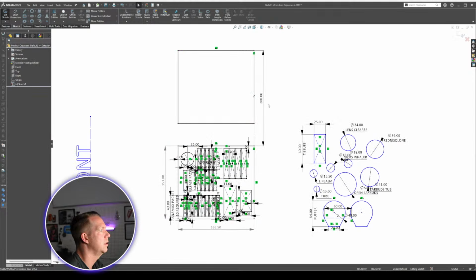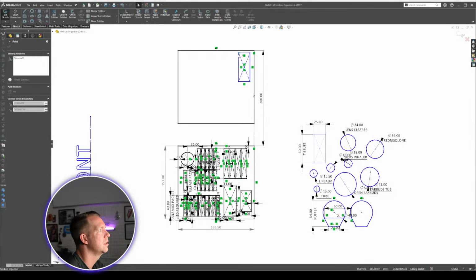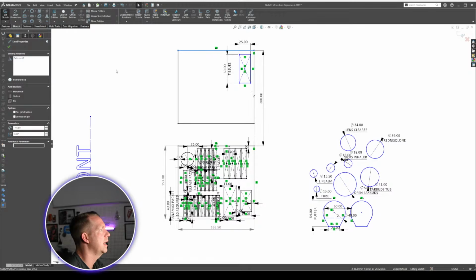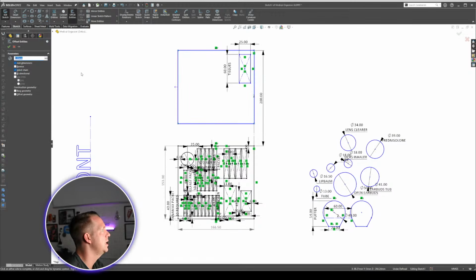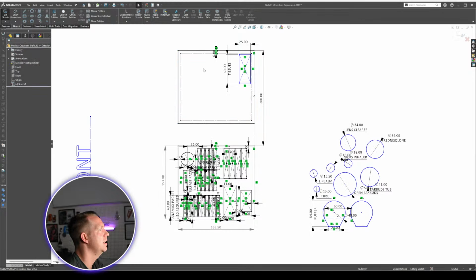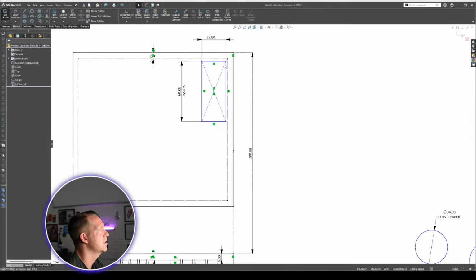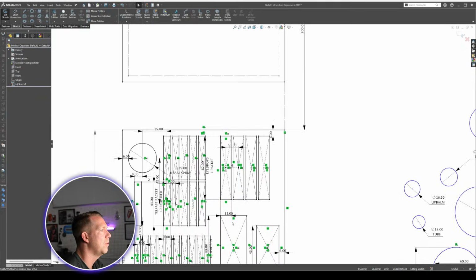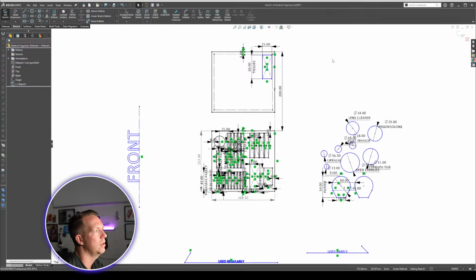Okay, there we go. Now I can grab all of these things and see if they're going to fit. And if I want to do it really accurately, I'm going to select that chain, do an offset, 6 millimeters, reverse, and make the offset as construction, because that's kind of my guideline for if I want the same spacing from the side on everything.